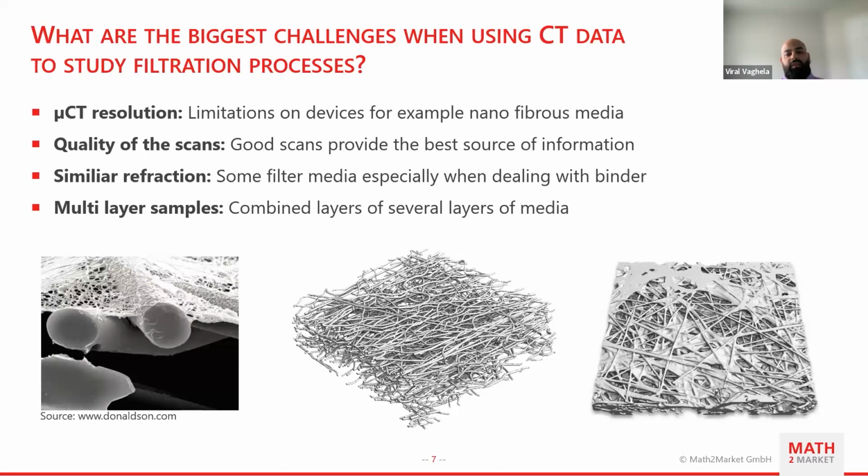Okay. And there was a similar question: how long does it take to simulate a digital twin for filtration simulations? And what are some of the properties we need to set in terms of parameters about contaminants and fluid for filtration simulations? Yeah, so when we have the digital twin, this mostly depends on the complexity of the filter media. If it consists of just two fiber types and one layer, it's rather fast. If you have several layers, binder and different fiber types, of course, it gets a bit more tricky, but it's possible in the software anyway.